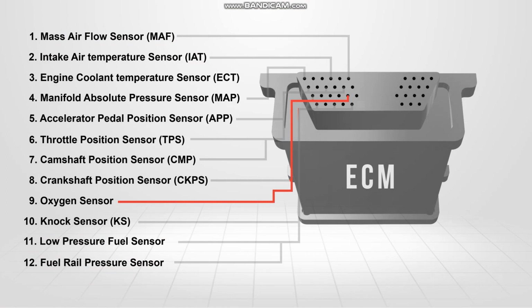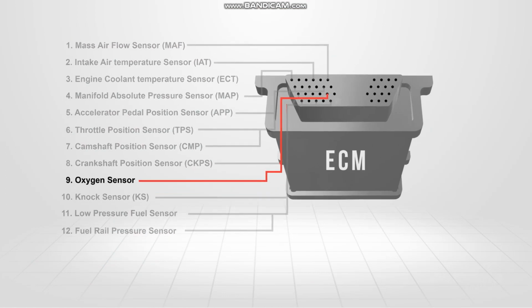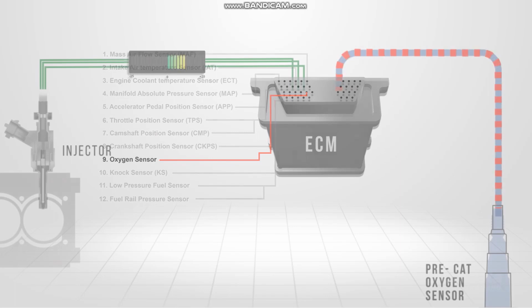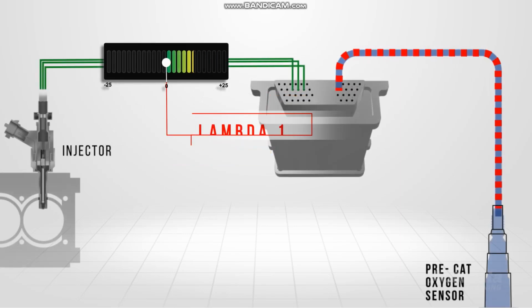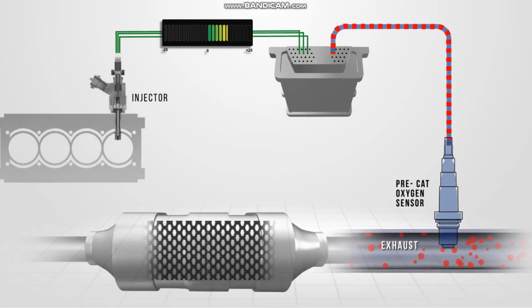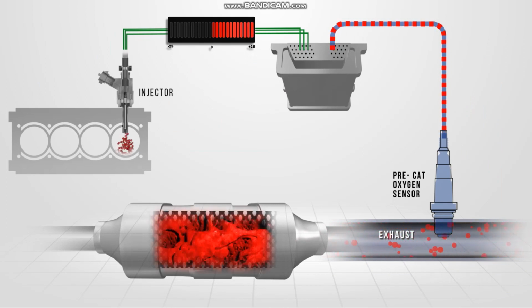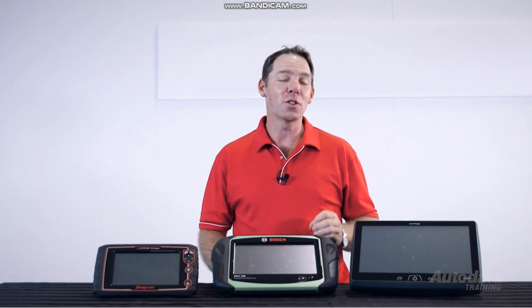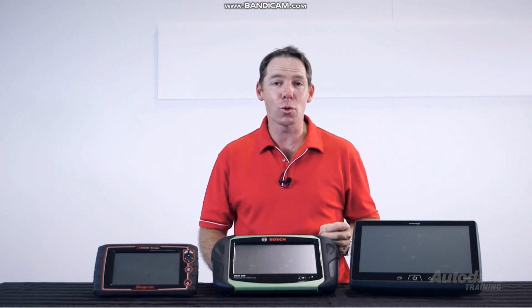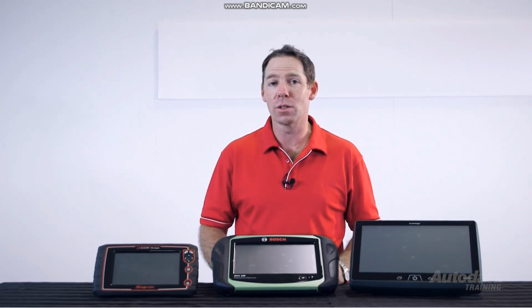Monitoring is achieved on a gasoline engine by careful control and adaptation of numerous engine parameters and operating conditions. Fine mixture control is the most critical aspect for efficient conversion. Anything that has an adverse effect on mixture control has the potential to cause permanent damage to the catalytic converter, which in turn will cause the vehicle emissions to increase into an unacceptable range. This mixture adaptation can be viewed on a scan tool as short and long-term fuel trims. These are critical values when used for diagnosis.